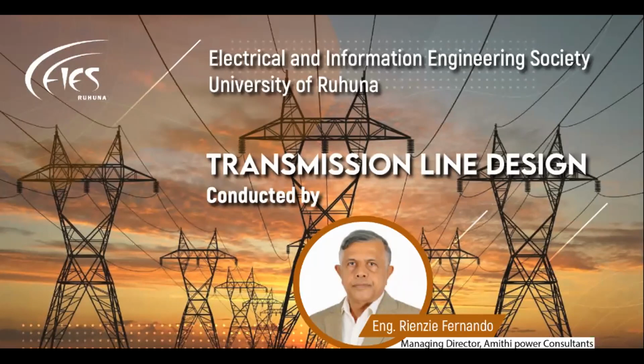So the way of earthing is what you call counterpoise earth. It's just a conductor. Okay, we'll say a 75 millimeters square or 120 millimeters square conductor joining the four tower legs, and then taken out to a certain distance and earthed with a rod.